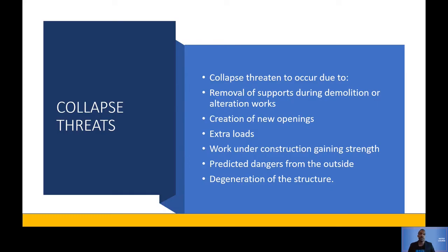If you're removing anything in the building, then you need to bring shoring in. Whether you're removing the bottom or the top, it doesn't matter. You need to bring shoring in for support for the removed part.